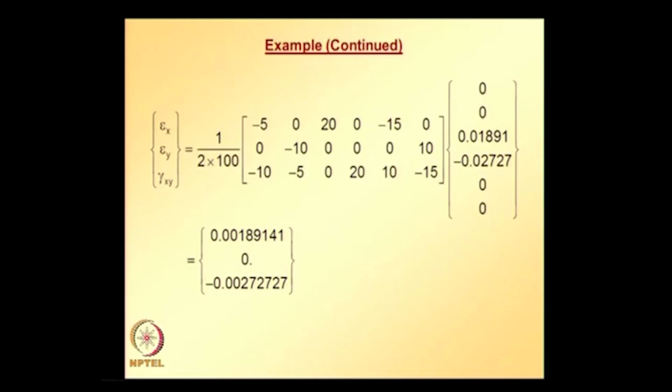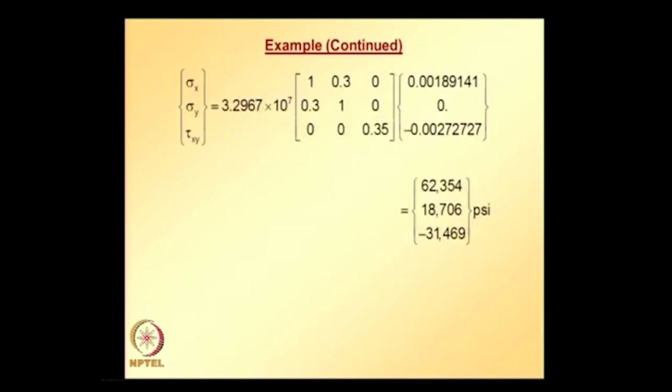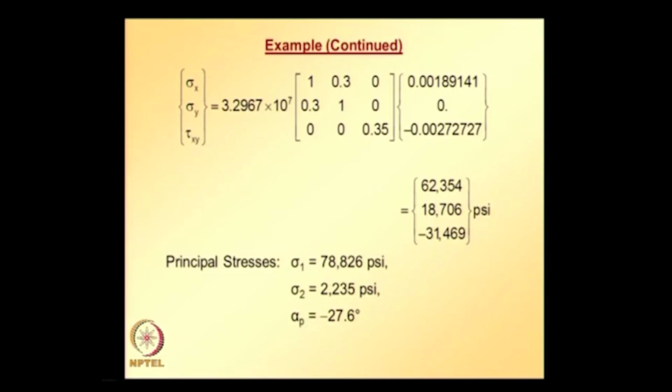These are the stresses for element 2, similar quantities reported as for element 1, that is principal stresses sigma 1, sigma 2 and the angle between sigma 1 and sigma x, and effective stress. Please note that strains are constant over each element and stresses are also constant over each element,